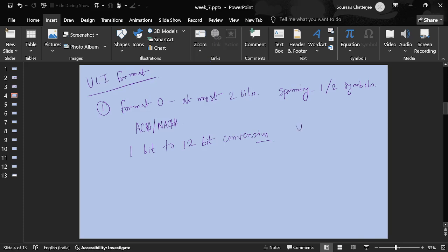And let's say I have a sequence, some arbitrary sequence, let's say -3 3 1 something of that sort, and what I'm transmitting is e to the power j phi n over 4, something of this sort. Okay, and let's say 30 such sequences are defined. For ACK, if we are transmitting let's say one kind of sequence, what should I transmit for NACK? Is there another sequence? I think a cyclic shift of 6. Okay, the same sequence only but cyclically shifted by 6.